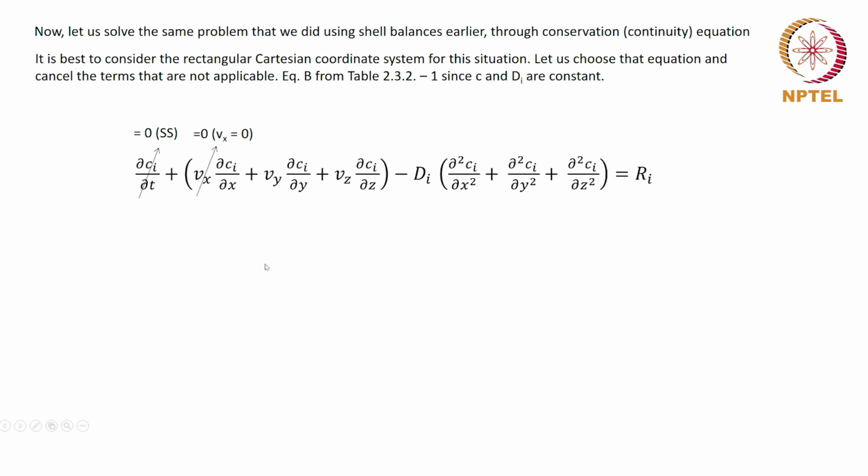There is no velocity component in the x direction, there is no velocity component in the y direction, there is no bulk velocity component in the z direction. There is no equivalent of the whole liquid moving. It is only the species that is moving in the liquid. That movement is taken care of in the diffusive terms, and there is no bulk motion here. The liquid is stationary or the system is stationary, right.